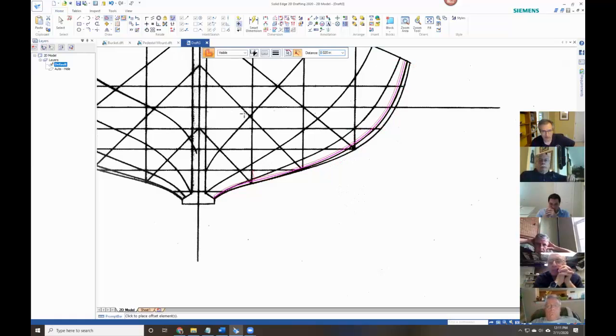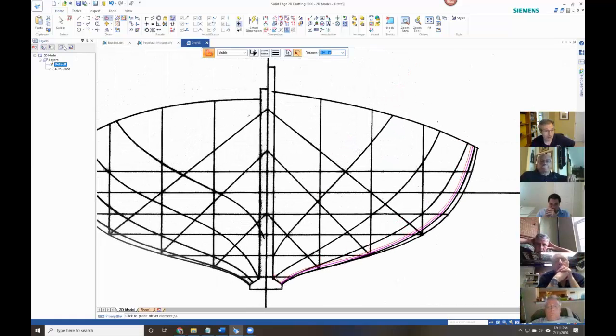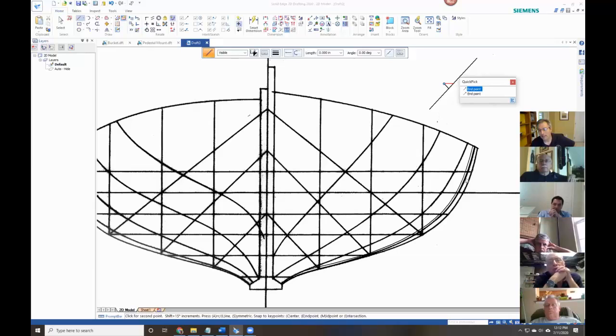So when you get up to here, if you're looking down on top of it, what I just did was move the body plan inward 0.02 inches, but the plank thickness is actually in this direction. So it's actually not accurate. It'll be very accurate at certain points of the hull and very inaccurate at others.